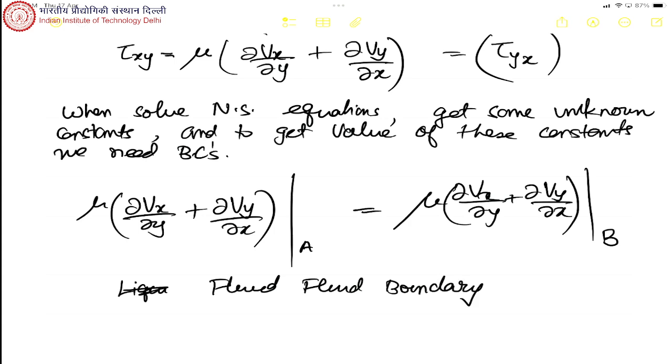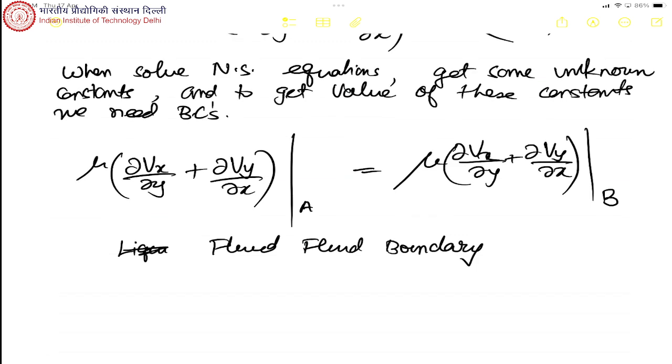fluid boundary. On the boundary where on both sides you have fluid, when you equate the shear stresses, you get this. Now you see, I am not using Newton's law of viscosity, which we used in the first lecture on fluids. The reason being, now I have a general expression, so I will use this. And this equation will give me then, so we will have this thing.